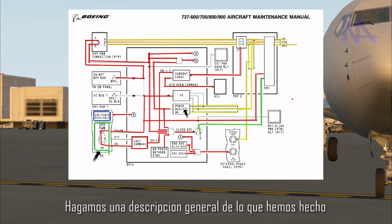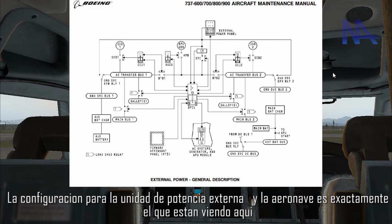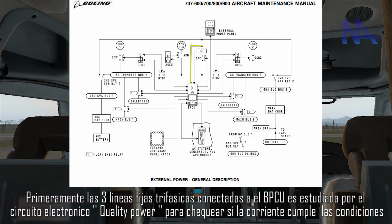Let's make a general description about what we have done. The configuration for the ground power unit and the airplane is exactly what you are seeing here. The components that create the electrical system to this point work as the BPCU orders. Following these steps, the protection and indication of the system works. Primarily, the three phase lines connected to the BPCU are sent to the electronic circuit of power quality in order to check if the current fulfills the conditions.